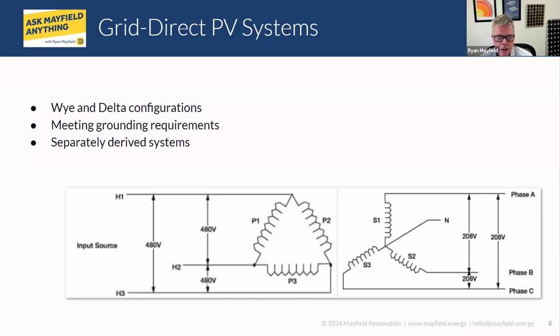Yeah, and that's when we're talking straight grid type PV, not energy storage at this point. It's been the Delta on the utility side and the Y on the PV side. Not every inverter requires that neutral. You can install some inverters without the neutral, but what we've been seeing is those deltas on the utility side are typically what we're specifying and how we're engineering things. And I guess, Nick, if you could comment a little bit about why a utility would want to see a YY on both sides?